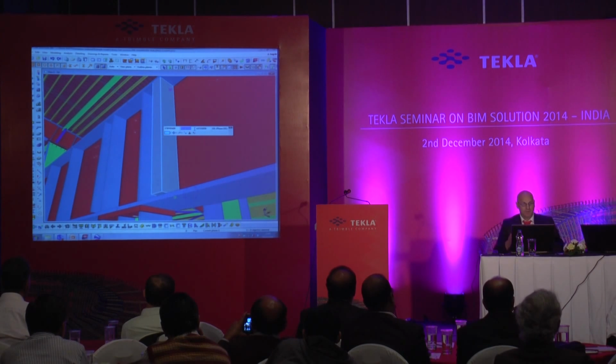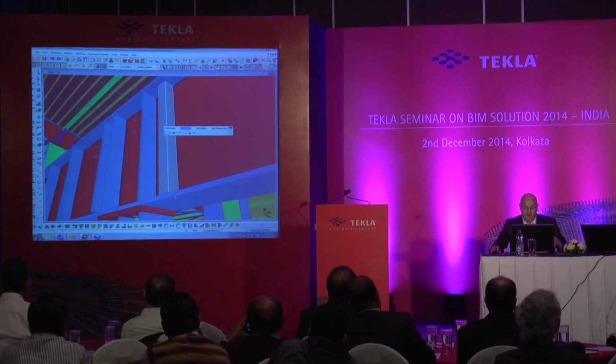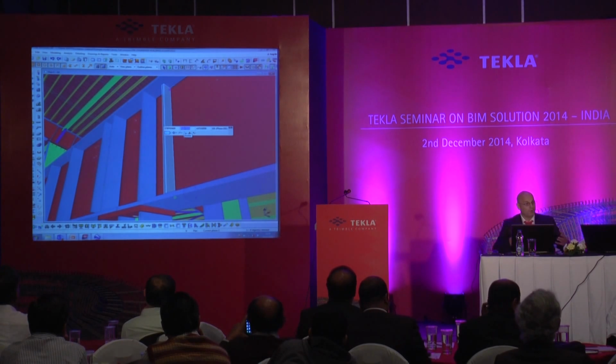So as a detailer, what I'm doing is sitting there creating this object. At the moment, that's 215 wide. Let's make that 115. So click and make it a different size. Okay, I'm going to make this 30 by 115. So you're just putting the object in there and changing it to match what's required from the drawings.